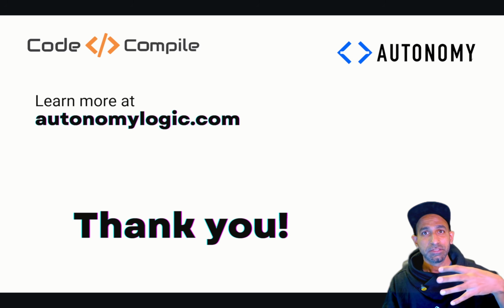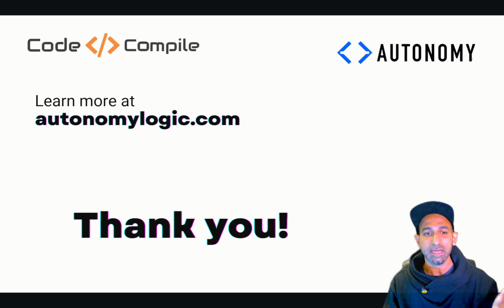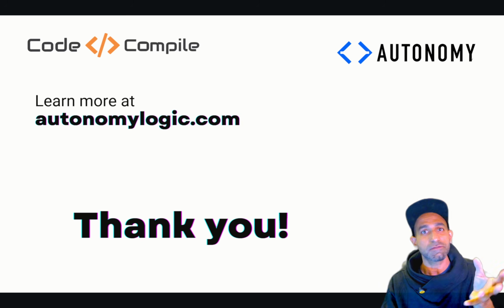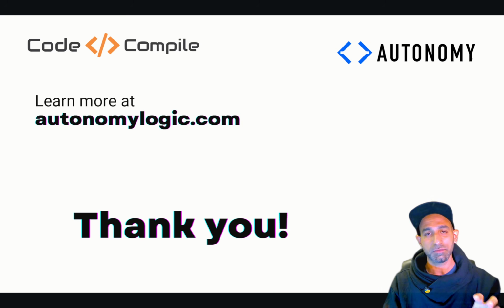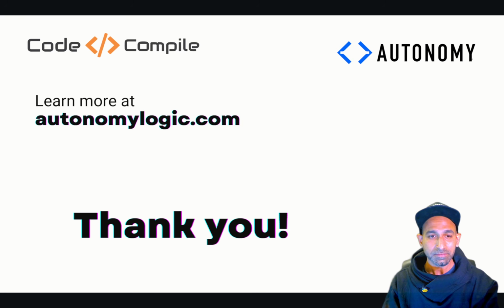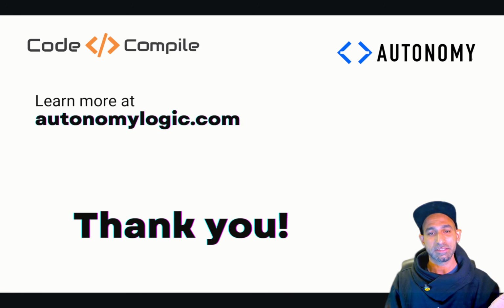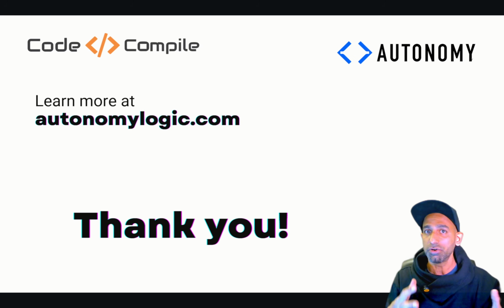All right. So traditionally, if you build such a system, you need a dedicated PLC, you need a SCADA system, you need proprietary software licenses, and that comes with the budget, right? And most importantly, you have to be at the location to do the commissioning and installation. But nowadays, with the latest technology, you are able to remotely program your PLC with a solution like OpenPLC running on the edge device, like a reComputer. You don't need a real PLC. You can just work on the edge device. And the other hardware is the same.